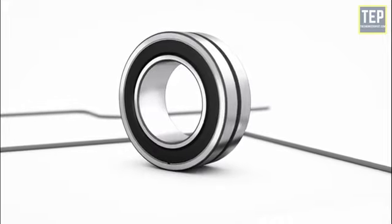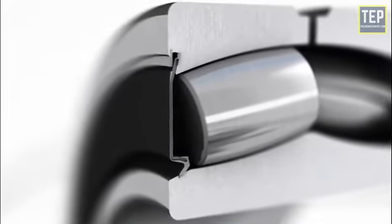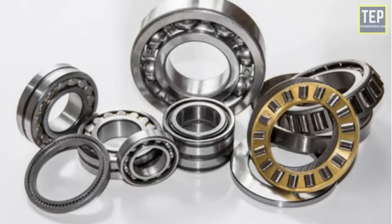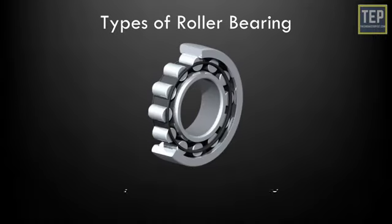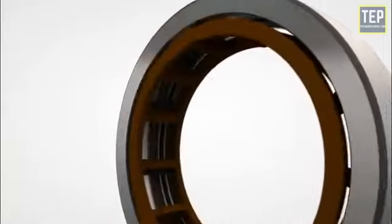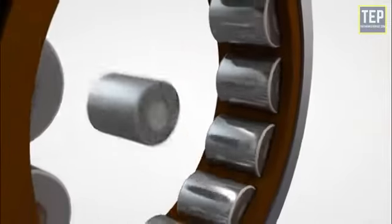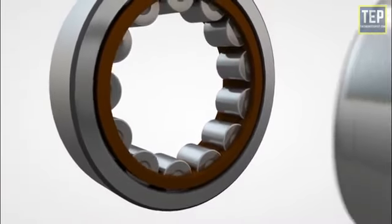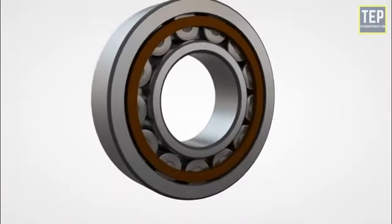Roller bearings contain cylindrical rolling elements instead of balls as load carriers between the races. In roller bearings, there are also various types. Cylindrical roller bearings use line contact between the rolling elements and the raceways, which optimizes the distribution of stress at the point of contact. These cylindrical roller bearings have a very high radial load rating. Depending on the design, they may also be able to transmit limited amounts of axial loads.